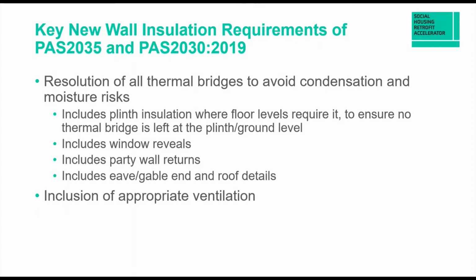So we need to make sure that we're addressing window reveals, party wall returns, eaves and gable ends, and including the appropriate ventilation. So the plinth insulation is one of the biggest ones that has caught people out. So there are different ways of resolving the thermal bridge at the ground level of a property, and it's effectively where the EWI tends to stop at the DPC, DPM on the outside.